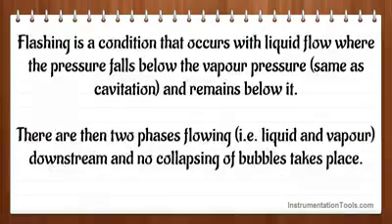Flashing is a condition that occurs with liquid flow where the pressure falls below the vapor pressure, same as cavitation, and remains below it. There are then two phases flowing, i.e. liquid and vapor, downstream, and no collapsing of bubbles takes place.